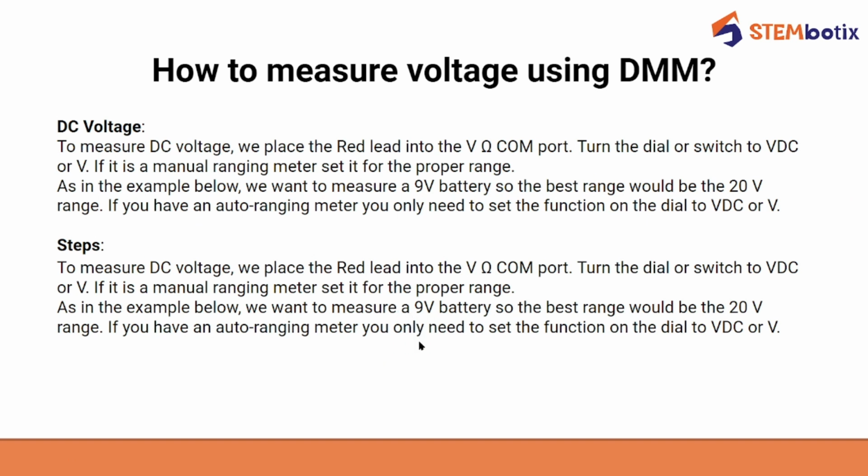This is a manual meter, but if you have an auto ranging meter, you will need to set only the function, meaning you want to measure voltage, so you will have to select just the voltage quantity.